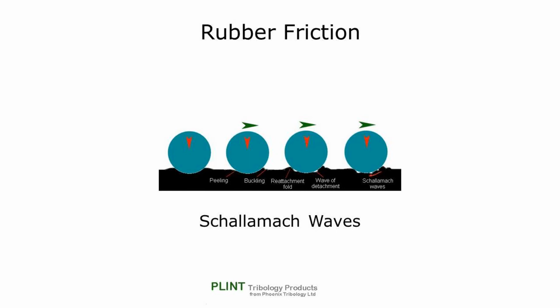Before the rubber can buckle, it must first be peeled from the rigid counterface, and the energy required to do this generates significant frictional resistance. At the trailing edge, there is a requirement to peel apart the contact. Local recovery and slip can give rise to reattachment of the rubber at the outermost edge of the contact. The process is cyclic and gives rise to variations in friction.